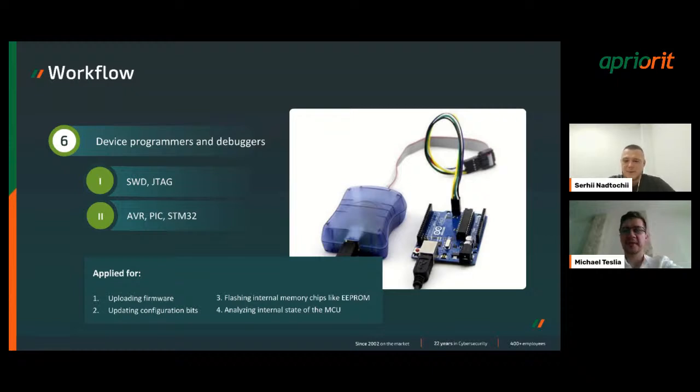Oh, yeah, of course, because I've just recalled one interesting case from my experience. We used a board with just 8 LED lamps for debugging the keyboard firmware instead of a debugger with a UI. It was quite an interesting experience, because these lights represented digits in binary format, and we really based our theories and debugging on that, knowing only some of the binary error codes.